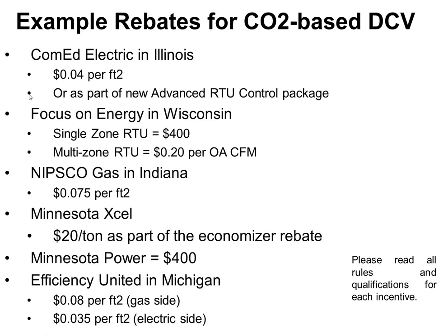So then what happens in each zone is if my particular zone needs more fresh air, my CO2 rate has gone up because everybody showed up to the conference room, if you will, I will first tell that particular zone to start opening up its damper. And then if that guy can't cut it and he opens up and he still can't bring the CO2 level down, then that damper will tell the ventilation damper outside to increase his fraction of outside air.